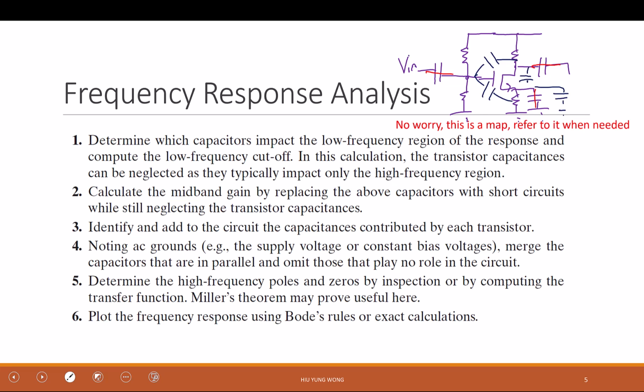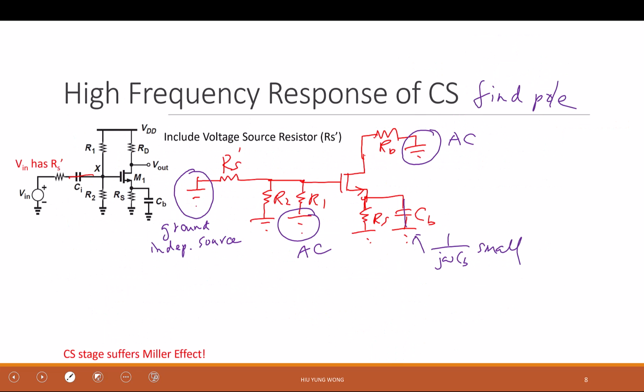Because this is a large capacitor. And then you may say, what if I cannot short it? Then you did not design a good circuit. You need to increase the size of your CB. Okay? And what if I'm not allowed to make it large? Then it is the limitation of your product. You either don't sell it or find another topology, right? You already hit the engineering limit. Okay, but in this class, we assume it works. And since it works, then CB needs to be shorted.